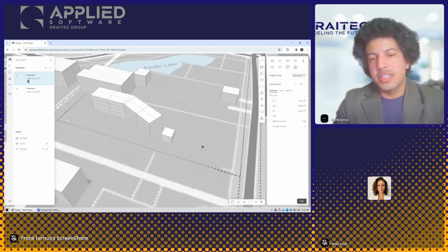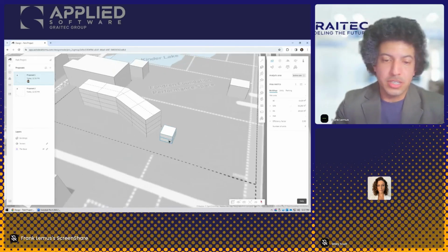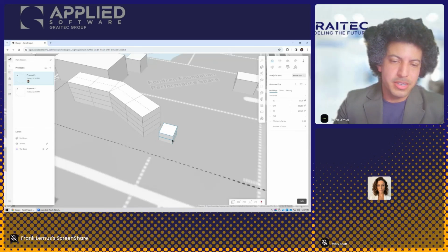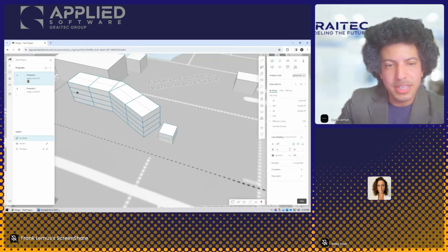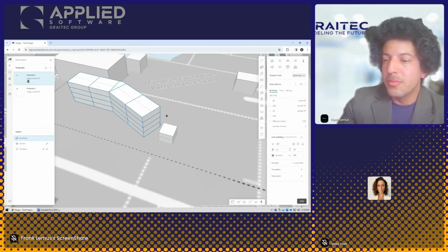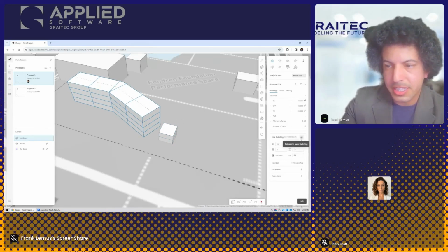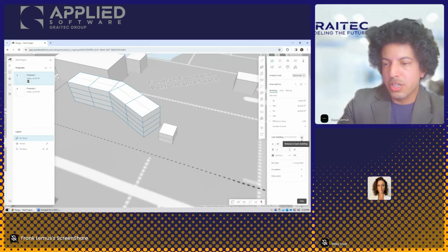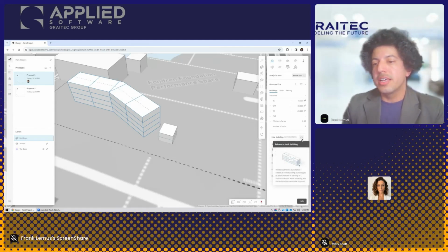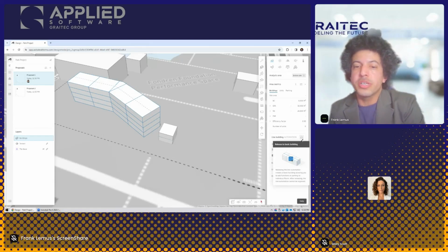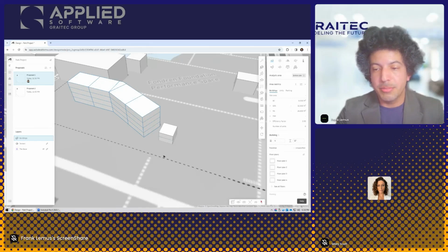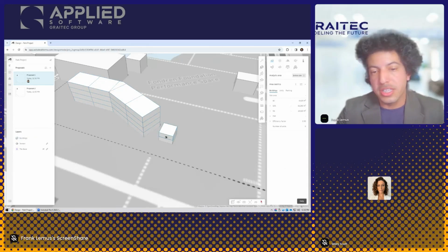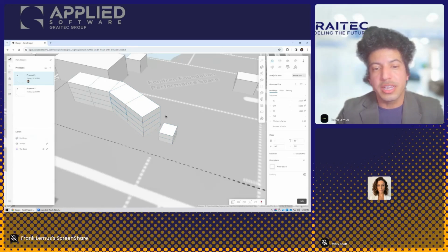All right, very cool. So far we've got these two buildings, but notice how, when I select this building, by default it allows you to select either floor. The other building selects as an entire building. Why? Well, if you look at this area down here, which is like the properties palette in Revit, this will tell you why. That little chain symbol is a new thing, and what it's saying is, look, it's all one unit. If you want to break it up into multiple units, just click on that symbol, and now you have, just like this one down here, individual sections and individual levels that you can select, all of that sort of thing.